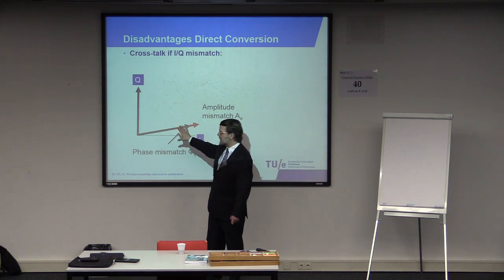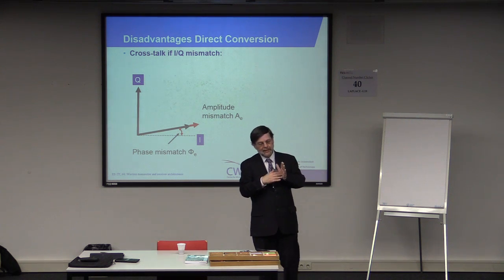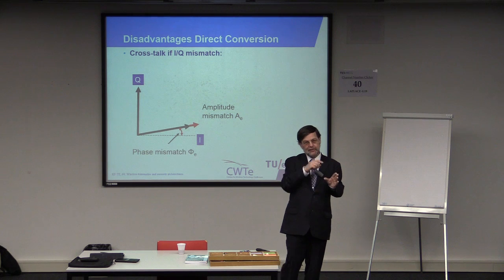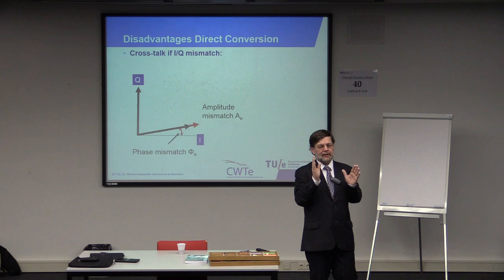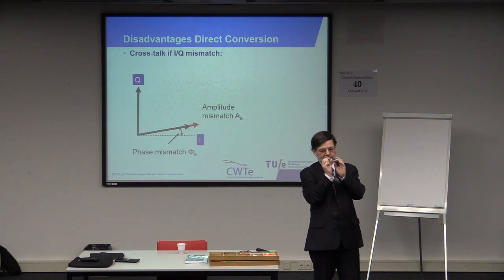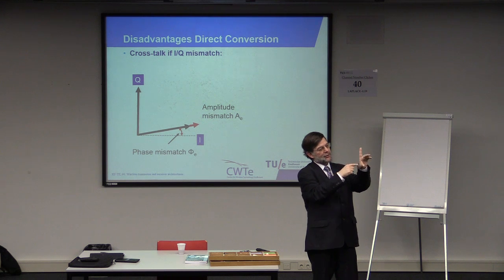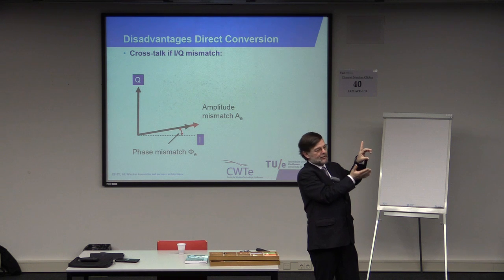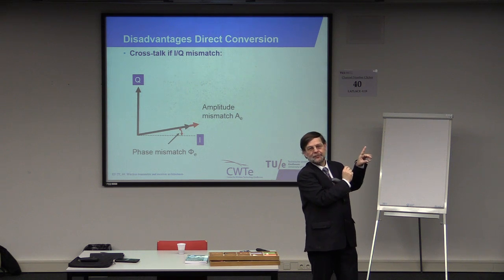One part that is decomposed correctly in I and Q, and one part that is what we call leaking, that's decomposed with the wrong sign of the frequency. So if I have an amplitude and phase mismatch, and I put in an input signal, and I'm looking at the positive part of the spectrum, then I should have a signal that completely rotates this way. But if I have a small mismatch, then mostly it rotates this way, but a very small part rotates the other way.